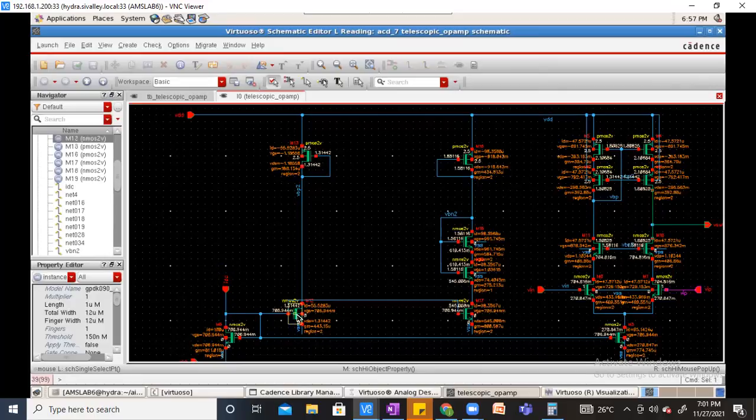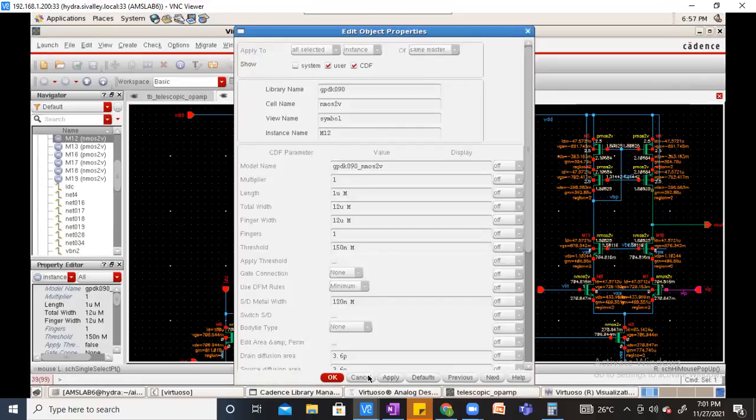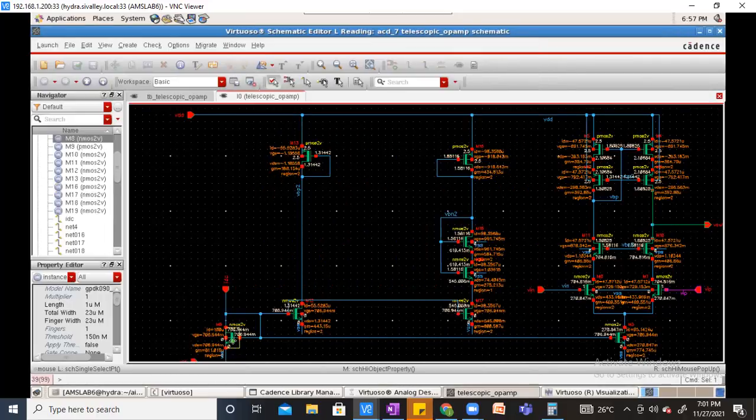So I use, you can say, 12 here, right? 12 means here it is 24, 23. So it's already 50%. So I step down by half. So basically the maximum current that can flow in this branch is half of the tail current source, right? That's what I have used here. This part is clear?